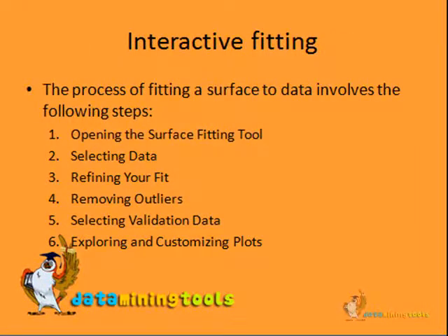Okay, so now we come to curve fitting. This is how the interactive curve fitting tool works, the process that is followed in MATLAB. First of all, we open the surface or the curve fitting toolbox. We select the data, we refine our fit, we remove outliers, we select the validation data, and then we start exploring and customizing the plots. So now let us start with an example.